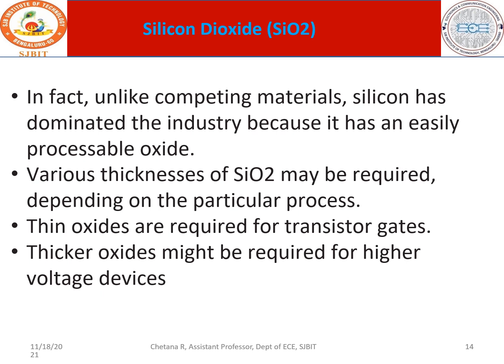At every layer of fabrication we will be using these. In the first stage we use thin oxide. In the second stage again we have oxide, and that becomes your thick oxide, for the only reason that the bottom layers are protected. Thin oxide is meant for the gate region, and thick oxide for the regions where you have voltages given for the source and for VDD.